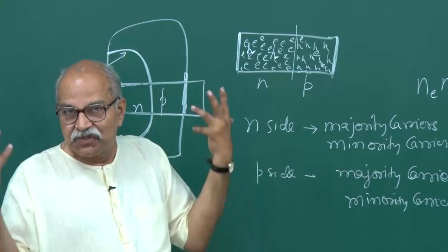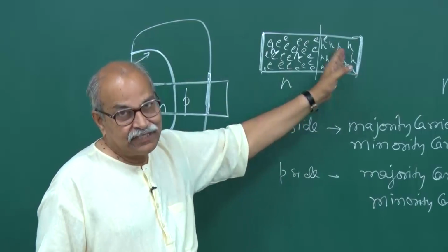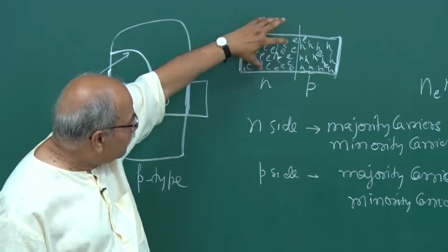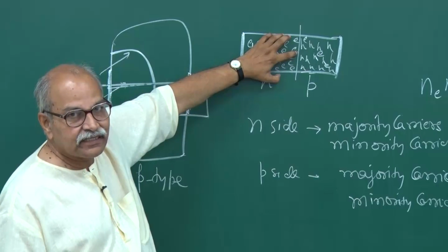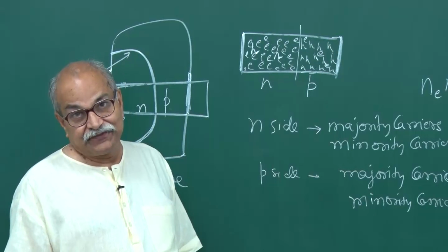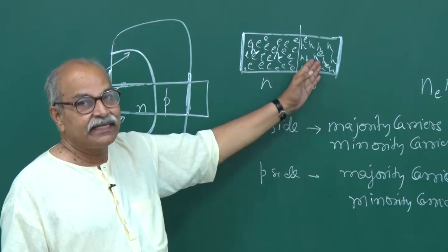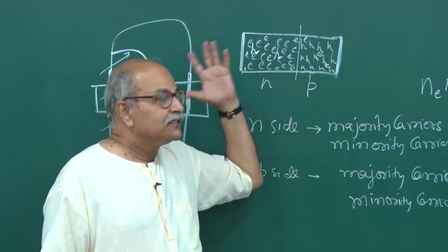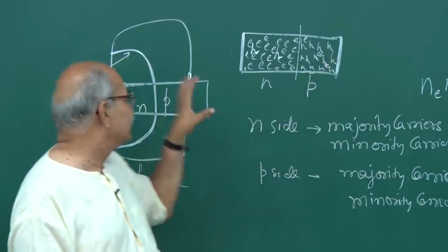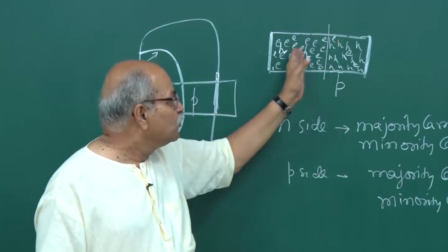So, all that usual electron movement and hole movement is allowed in this entire wafer, in this entire material, and therefore, having a large concentration of electrons here and a very small concentration of electrons here is a very non-equilibrium situation. If you have such a huge concentration gradient, and if the movement is allowed, they are allowed to go from here to here. Remember, this whole thing is one single crystal on which you have done all these diffusions, and therefore, that movement is allowed.